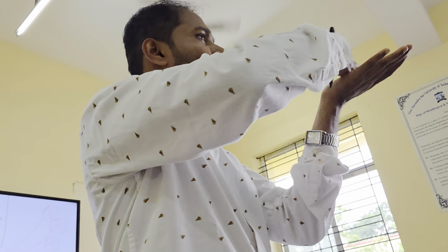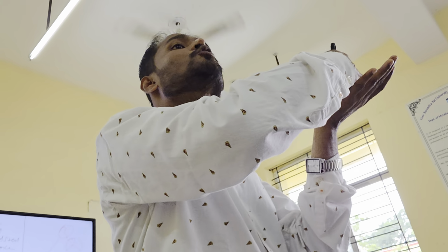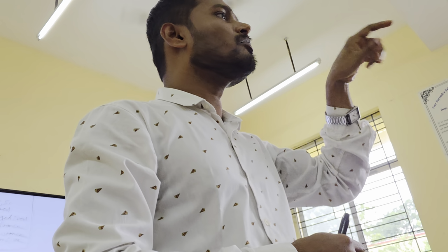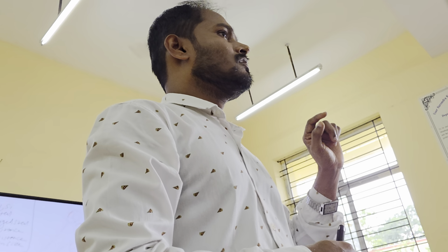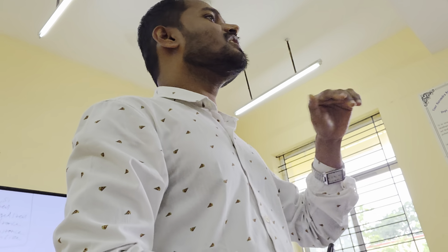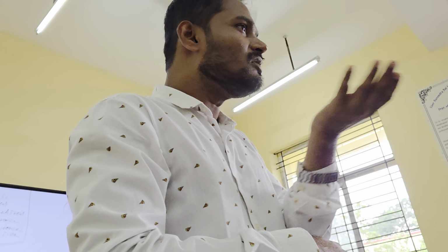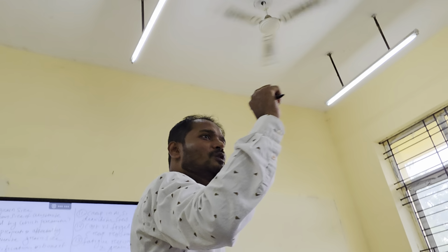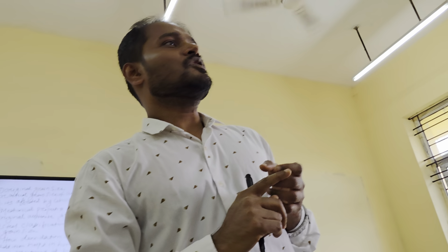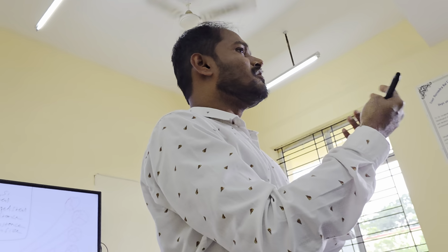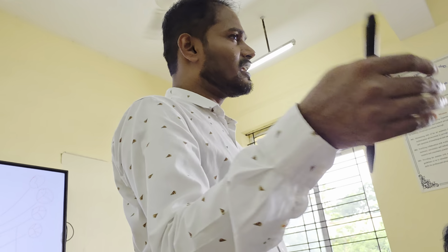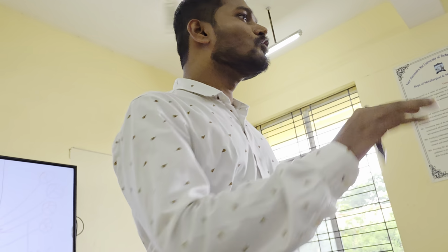One is fixed, one is moving. There is a relative motion between two bodies in contact. So what will happen? Some material will get eroded from one surface. Okay, fine. So basically erosion should happen on the material. It should not happen on the tool. Right? If the tool is weaker, erosion will happen, right? So basically good machinability steel means less wear will happen on the tool. Actually we want a good machinable steel, then only machining will be easy. Tool wear will be less.